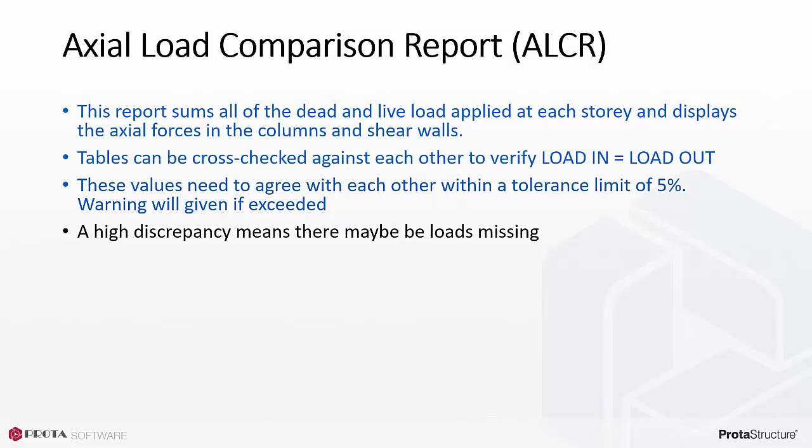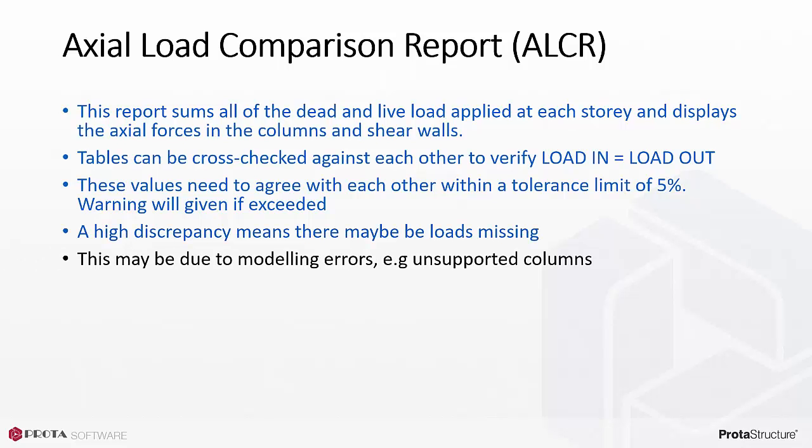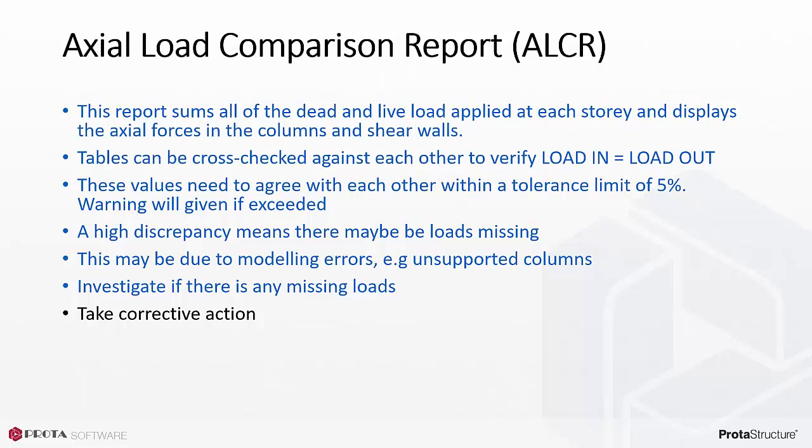A high discrepancy means there may be loads missing. This may be due to modeling errors, for example unsupported columns. You should investigate thoroughly if there are any missing loads. Go back to the model to take corrective action. Rerun analysis. Recheck the ALCR report.